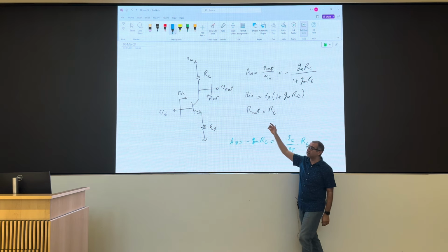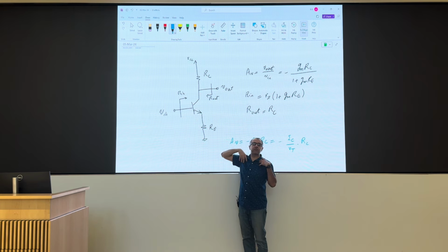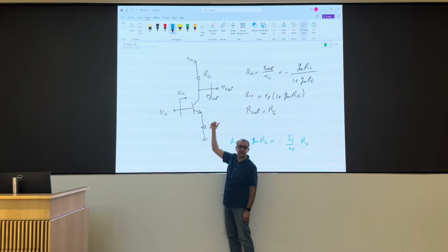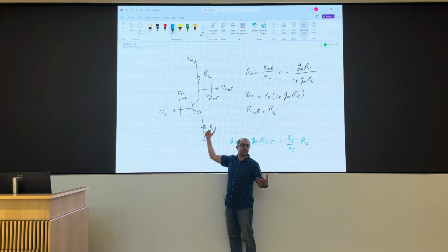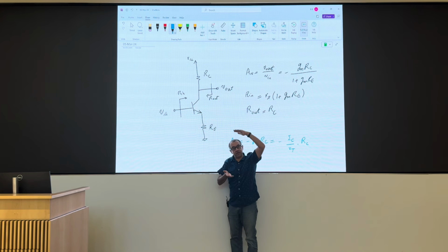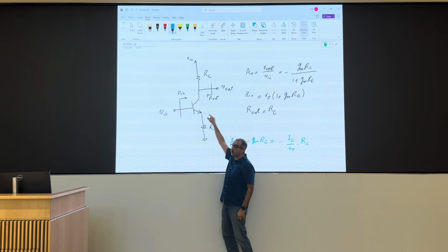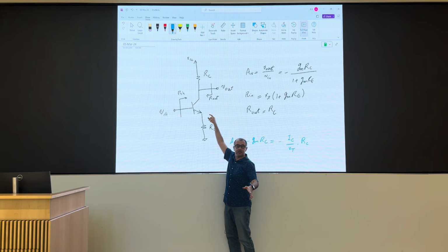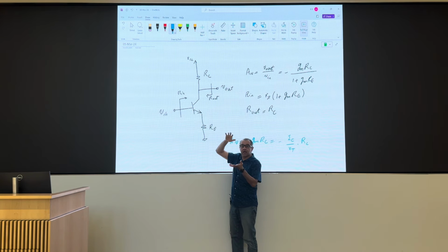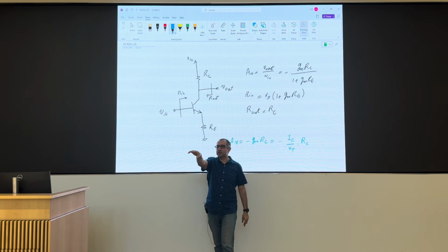And then for that reason, you can see that if I'd like to have a high gain amplifier, I would put VC close to 0, as close as possible to emitter. Why? Because I want to have a lot of DC voltage drop across that RC. It takes away my swing though, right? It eats my swing. Because then if I drop the collector voltage a tiny bit, I enter saturation. So I do that if I know the signal at the output is still small and I want to have the maximum gain.